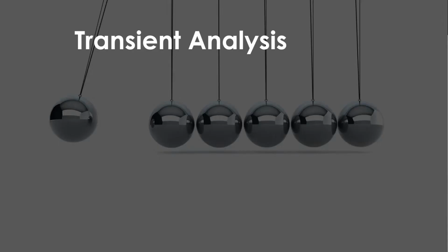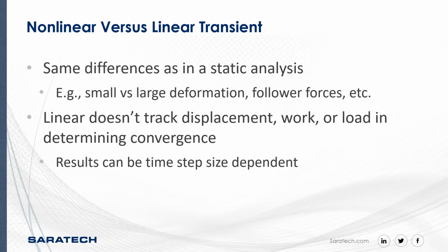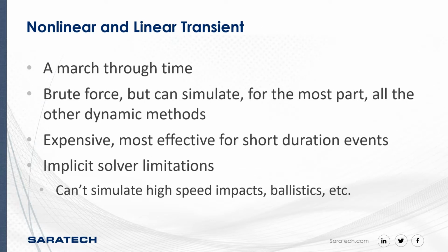So next up, we have transient analysis. We have nonlinear and linear transient. The easiest way to describe this is that it is a march through time. We're taking incremental time steps as we solve an ever-changing or time-based load. You can think of it as brute force, but technically you can simulate for the most part all the other dynamic methods because we are simply marching through time.